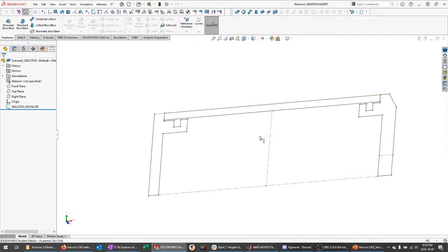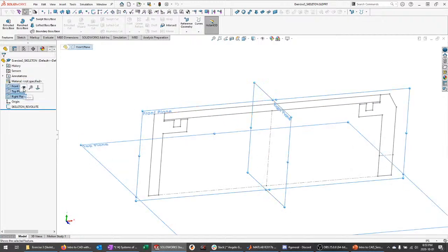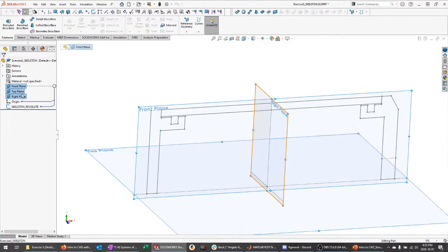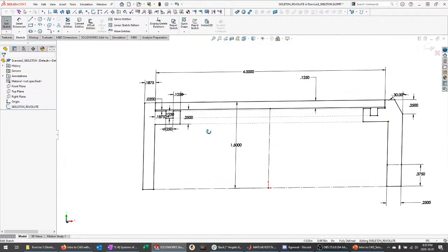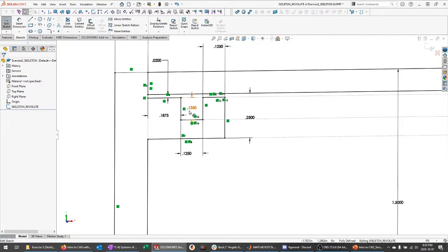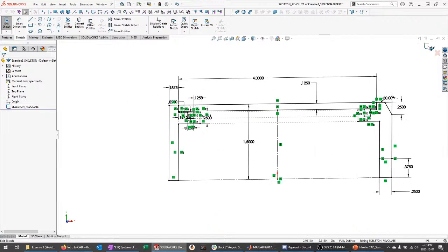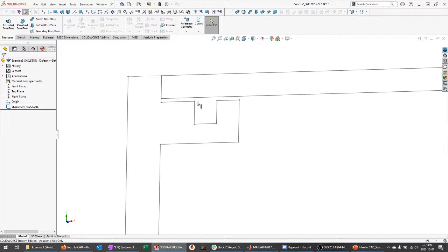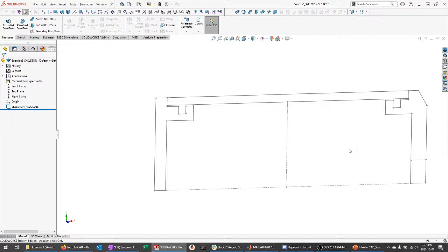All right. So this is a skeleton that we've prepared. Pretty simple one. It just has your 3 default datum planes and then 1 sketch. If you edit the sketch, you can see we've got all of our constraints and all dimensions, fully constrained. So let's say this is for a waterproof underwater enclosure. This rectangle corresponds to, if we revolve that, a tube, and then these 2 other closed contours will create end caps with O-ring grooves here. But the geometry of all those parts is interrelated.